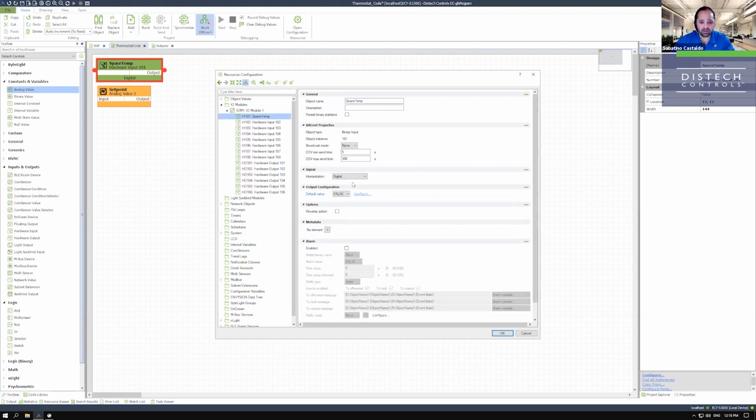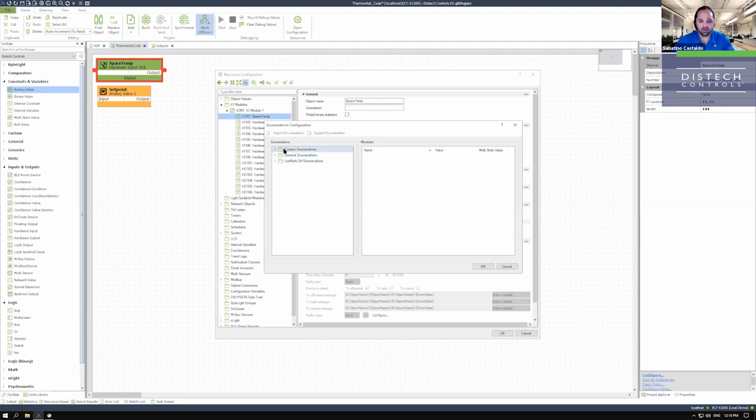So that was custom. Digital, very simple. Digital, true, false, or you could change this type. You could call it on, off, yes, no, manual, auto, start, stop for a Boolean type of interpretation. Typically, you would use Boolean. You wouldn't use enumeration for, well, you could maybe for a hardware input, but not for a binary value, of course. And if this input was set for something other than what you're used to here, you can also make your own by just going into enumeration and configuring your own custom enumeration.